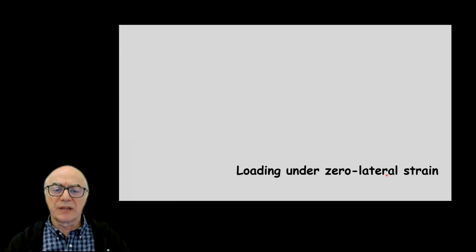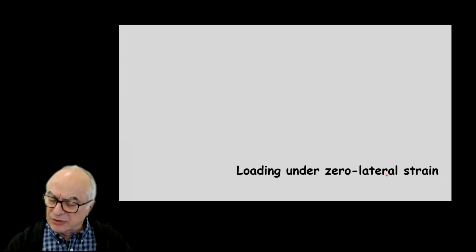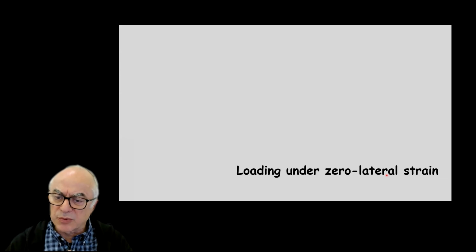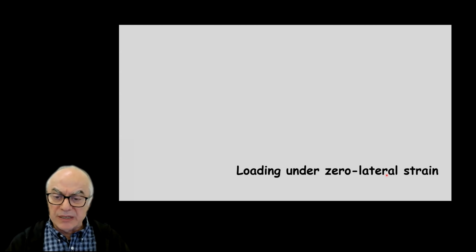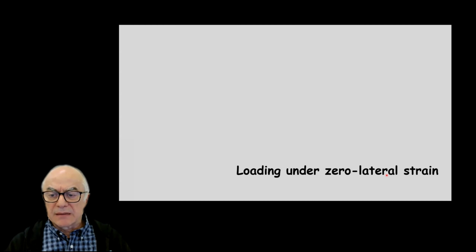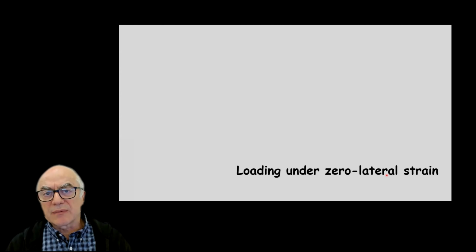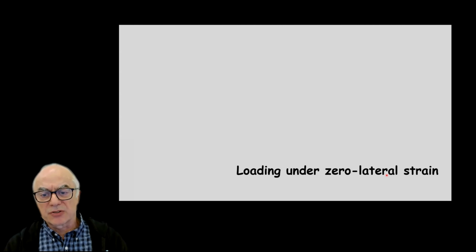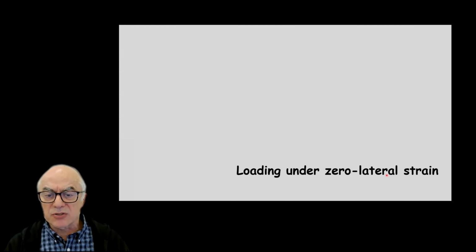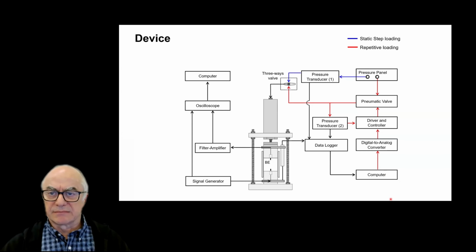So let's explore this one, and we have to recognize that the horizontal stress will be changing, and so the K-naught line itself will not have a constant obliquity per se. But in this case, we are not wondering about the accumulation of shear deformations, we are wondering about the accumulation of volumetric strain. So this is the case that we are going to show you some data.